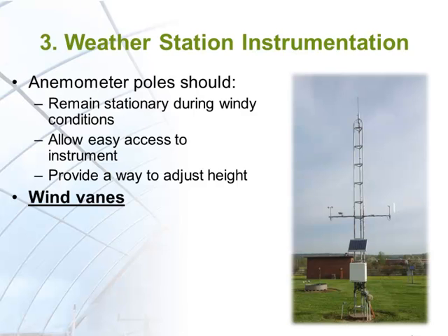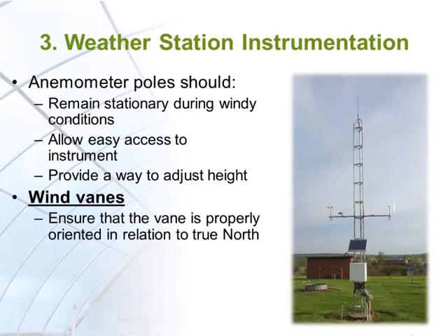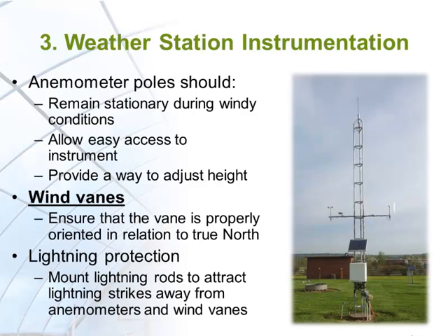For wind vanes, we need to ensure that the vane is properly oriented in relation to true north. The weather station also needs lightning protection. Mount lightning rods to attract lightning strikes away from anemometers and wind vanes.